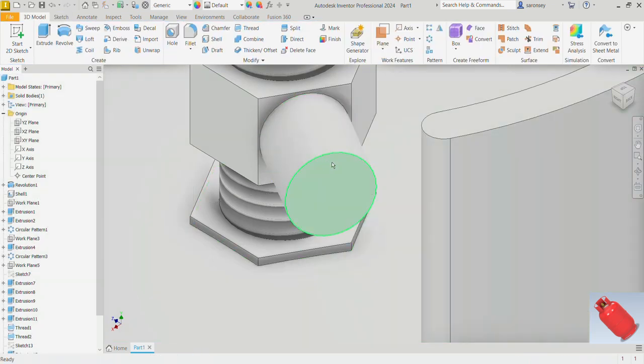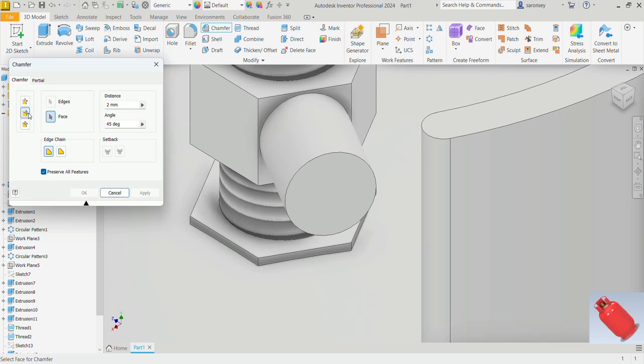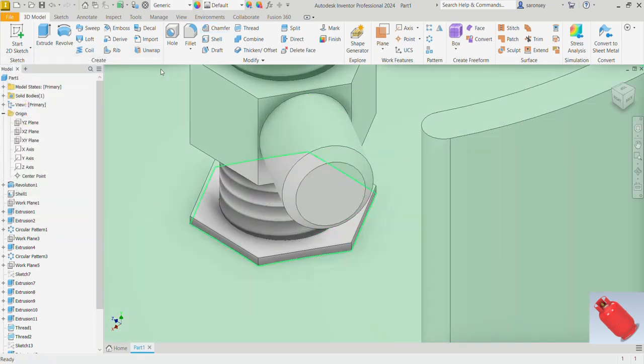That closes it. Now let me apply a chamfer. A chamfer is going to be the second one, distance and angle. It says we should select the face, so I'll choose this face. The edge, I will choose that edge. And the distance 2 mm is fine until we apply. And close this for now.